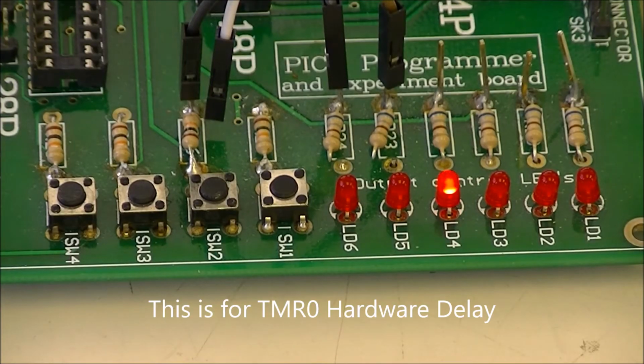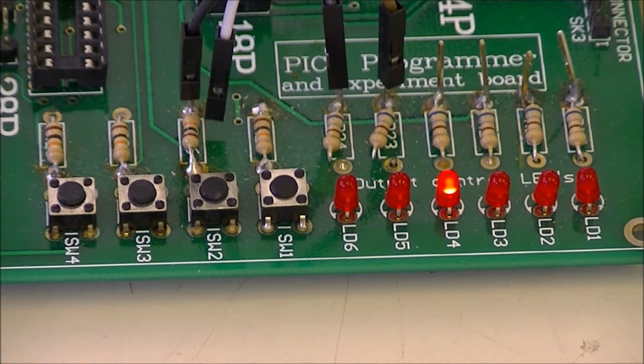Alright, this is a section of my K8048 PIC development board. Alright, big deal. I'm blinking an LED. What do you need to blink an LED? Well, you need to turn it on and off, and you need to put time delays. Delay it off and then delay it on so you can see it. Otherwise, it's just going to appear like it's on all the time and a little dim.